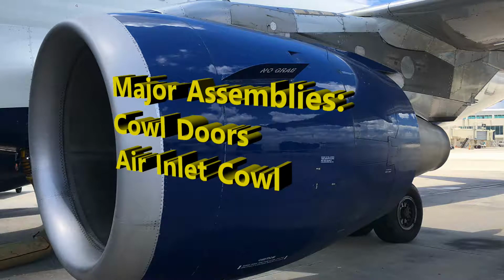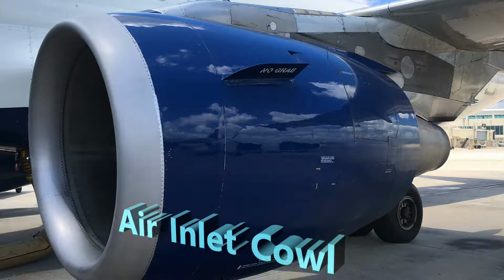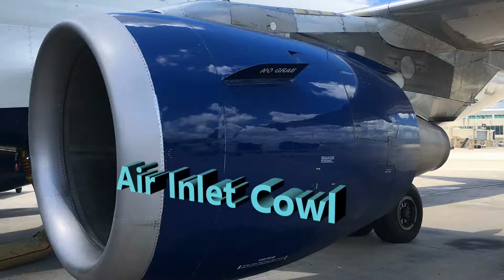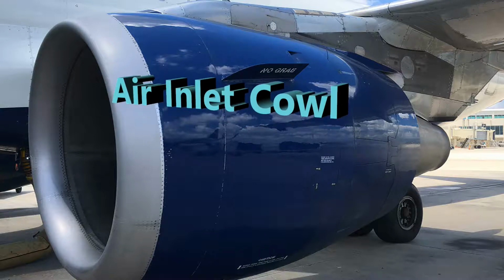And then you have your air inlet cowl. Your air inlet cowl is just taking in, obviously, air when it first comes into that whole powerplant, and that is attached to the front of the compressor case. Then you have the fan cowl doors that are there as well. They provide an aerodynamic surface between the air inlet cowl and the thrust reverser.